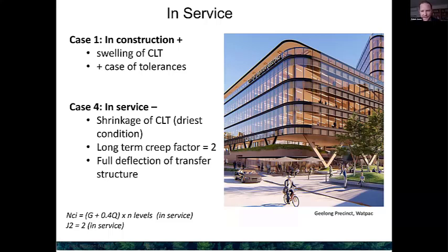And then in service, the two cases that are perhaps the most relevant are, firstly, understanding case 1. So let's say we install our building when there is moisture and swelling of our timber elements, we're going to be designing above. And then in service, in 5-10 years down the track, when the moisture content's going down and it's loaded up and you've got additional creep, we're going to have our in-service minus. So understanding the difference between the worst case scenario it's installed at in terms of height versus as low as it could possibly get as well.